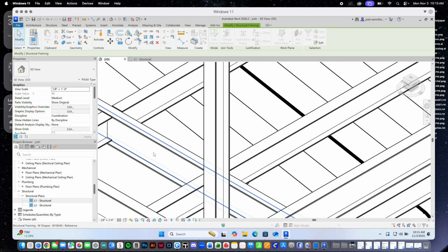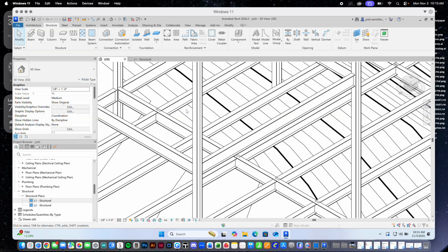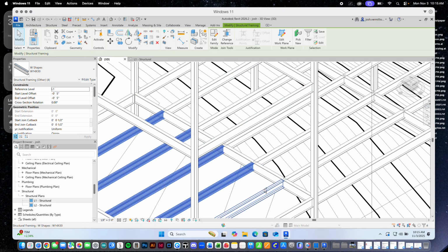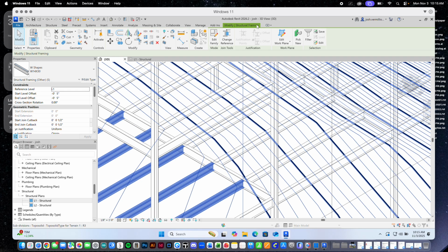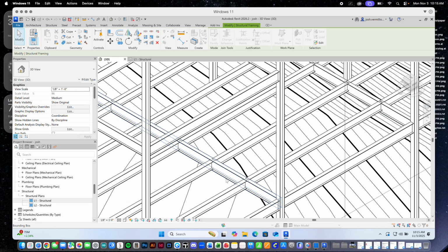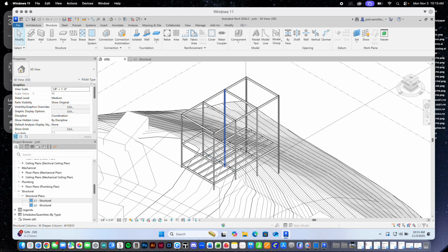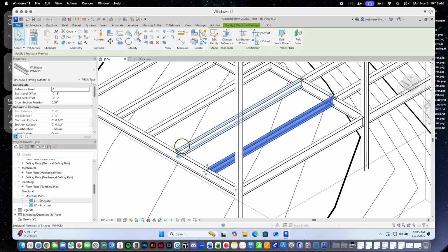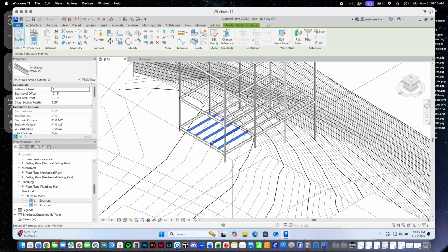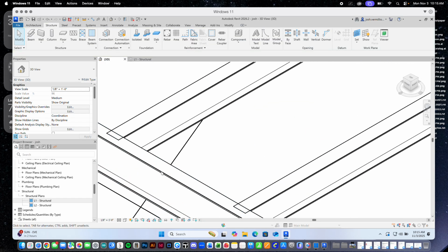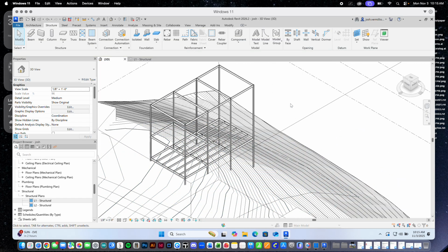All right, change that reference, select that web. And one more row, we'll do it twice because I have 2 ends of each beam. Change reference, let's select that beam web, there we are. Oh yeah, look at that. And the same thing over here. And I'll do this also for the roof and the second floor. Unfortunately, this change reference thing is kind of a drag. You're going to have to do it repetitively, I suppose.